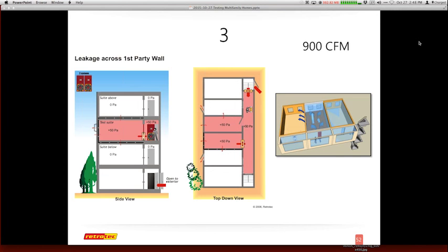So now I'm actually going to do the unit on the right. Now, depending on if you have this nice controlled hallway, and on the far end, I actually have closed the door. If I'm able to get enough pressure out of the hallway, I might be able to just open the door to the unit on the right side. And once I do that, I have to make sure I seal the windows or any other conditions, you no longer need a pressure relief on the other side. This is really only focused from one side, from the area that I'm testing. So I still have a pressure relief on the left. Once I open the door here, I have been able to create a neutral pressure on the right side. So now I have the hallway and the right side with neutral pressure, and my number went down another 200. So now I have 200 CFM that's connected between that common wall.